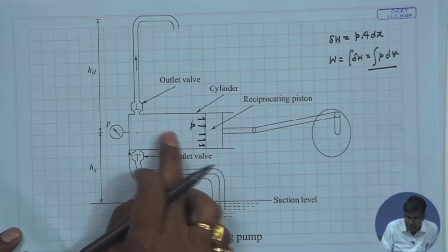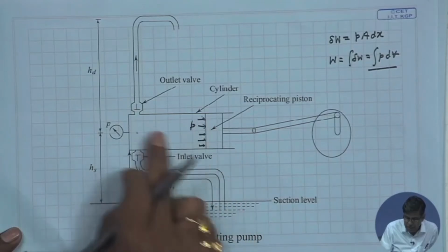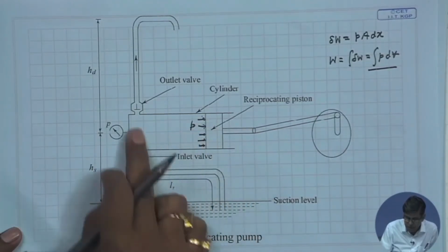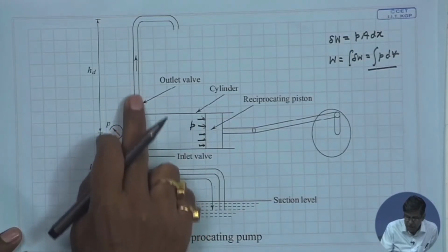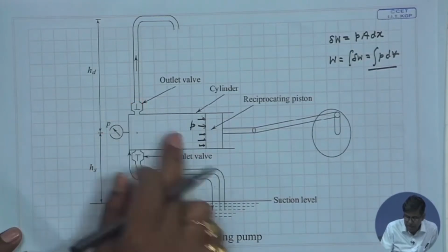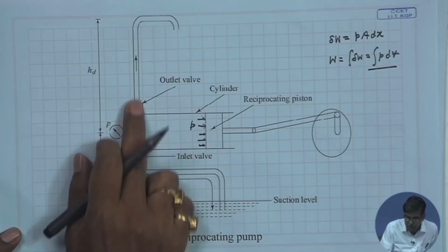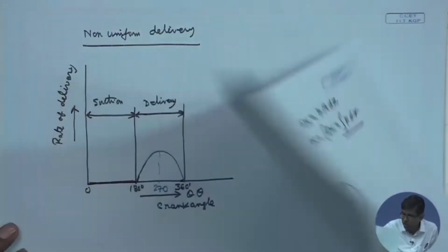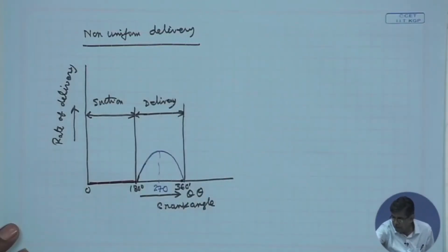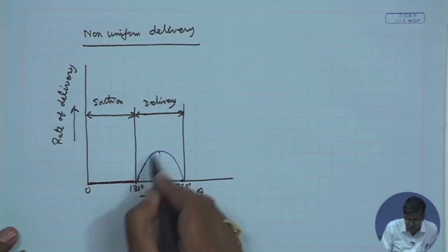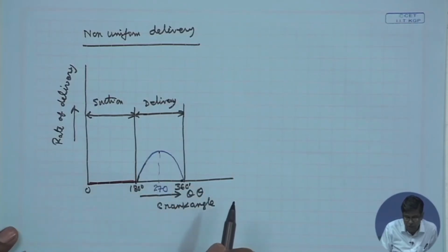This results in a variation in the flow velocity in line with the velocity of the piston, and similarly the pipe velocity only varies in magnitude by the ratio of the area. So, the discharge, which is proportional to the flow velocity, also varies in the same fashion as a sine curve. So, you see we get a non-uniform distribution.